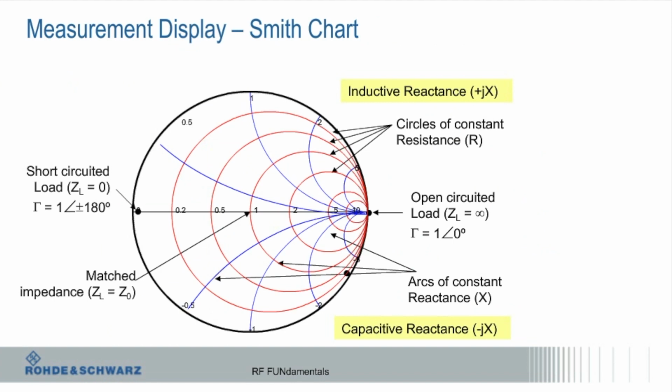Okay? So if you look on here, this is kind of the thing you've got to know about a Smith chart. After you've done a calibration, assuming you did it correctly, if you put a short on here, ideally, if it was a perfect short, and this is going to lead to a question, you'd get a dot out here, okay? And if I put an open on, I'd get a dot here, and if I had 50 ohms, here. And then moving down, you see here I have more capacitive reactance, and then moving up, I have inductive reactance, and that's on these circles.